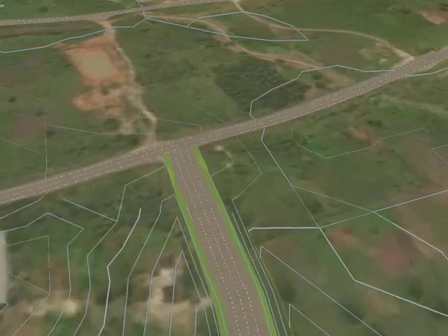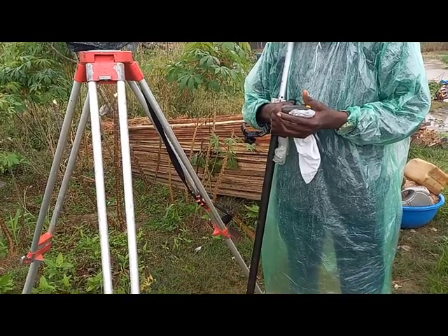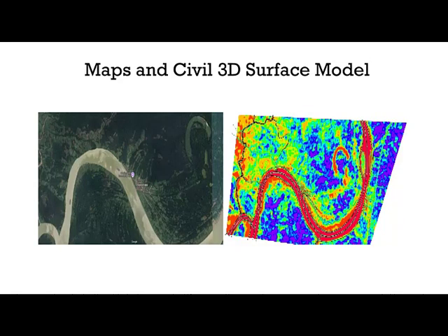That surface can be used for preliminary understanding of the site's proposed location for a project. So this survey you are doing with instrument is the actual values that you have on ground. So you can do one at your desk and you can do the other actually on site. So if you want to compare both, it's fine. But one gives you a general idea about the terrain and the nature of how the site is, which is very necessary. So if you have that preliminary information before you go ahead and carry out your topographic survey on site, it is quite helpful. So you have more information while you're on site.